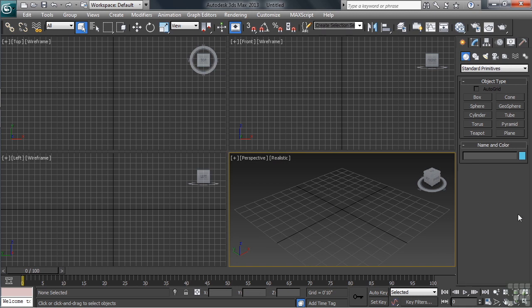Okay, let's start with the walls. Anytime you need to quickly add a wall to a scene, whether it be to the inside or to the outside of the structure, you can go to the Create menu, click on Standard Primitives, and head into a section called AEC Extended. AEC standing for Architectural, Engineering, and Construction.